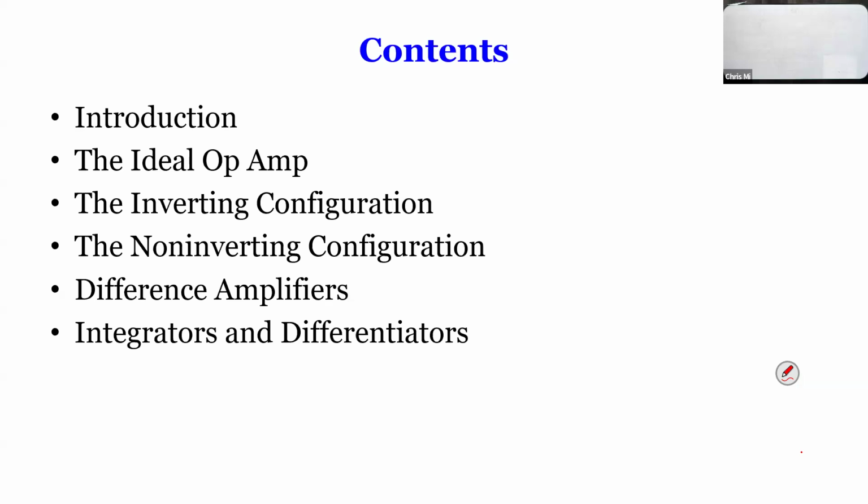And finally, we're going to cover a little bit of integrators and differentiators. Now, you probably learned this already in 210. If you have a capacitor with, say, a current coming in, the voltage will start to increase, so it integrates. And differential means the inductor, right? If you have a voltage coming in, the output is a differential of the input voltage, so it's the differential of the current. So L di/dt gives you voltage, and C dV/dt gives you the current of a capacitor. So we're going to see how they work in op-amps.